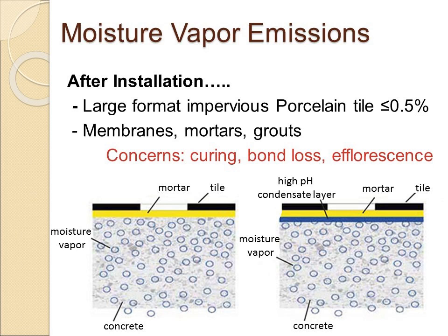If we're on a residential project, we can also look for signs of moisture, and we'll show you a little test that you can do, or look at the ground around the building and see if there are any conditions that could lead to hydrostatic pressure, where you're going to have literal water coming up to the surface, or areas with a lack of drainage, especially in construction, where moisture and water is going to come up against the building.